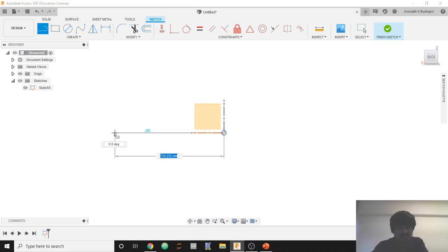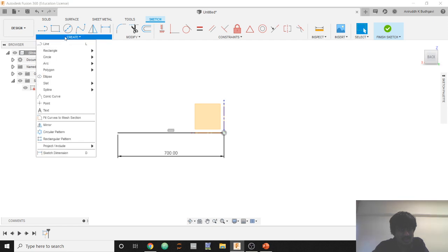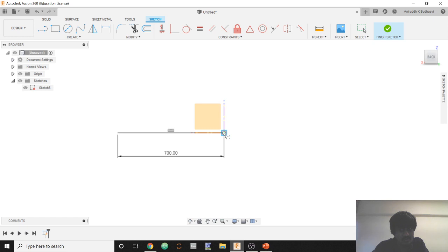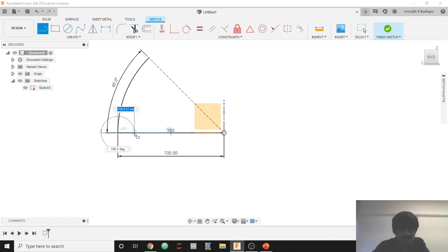Now what I'm going to do is a line of 700, and now I click create here. I choose arc, I choose center point arc. And I choose, let's say, 45 degrees. So, and I choose, let's say, 100.